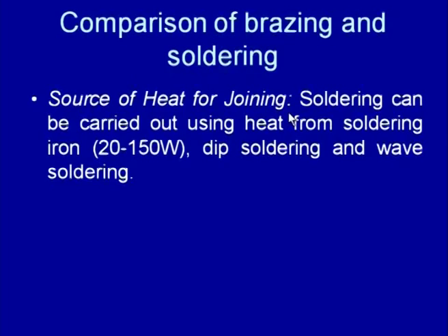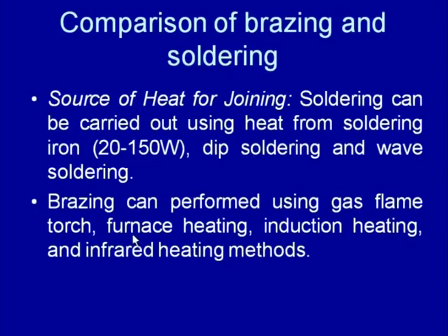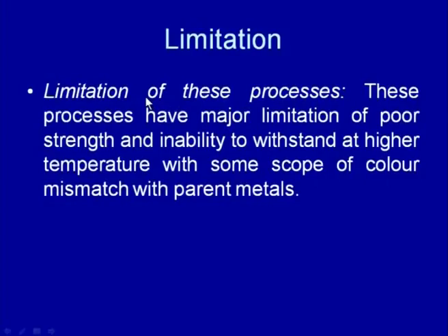As far as the source of heat is concerned, soldering can be carried out using the heat from a soldering iron, dip soldering, or wave soldering. Brazing can be performed using a gas flame torch, flame heating, induction heating, or infrared heating methods. But there are certain limitations associated with both these processes.